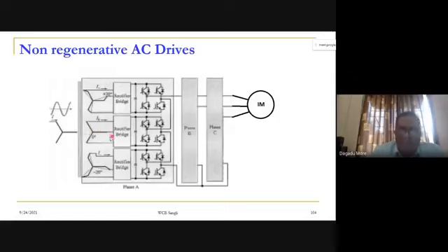Normally, our power transfer is one primary winding and one secondary winding. But here, particularly for this drive, we require one primary winding and 9 secondary windings. That is the complexity of this particular drive. So this is a cascaded H bridge multi-level inverter. Number of levels are 7. We require 9 rectifier bridges, an isolated supply for each H bridge, and then we are having a 3-phase transformer.